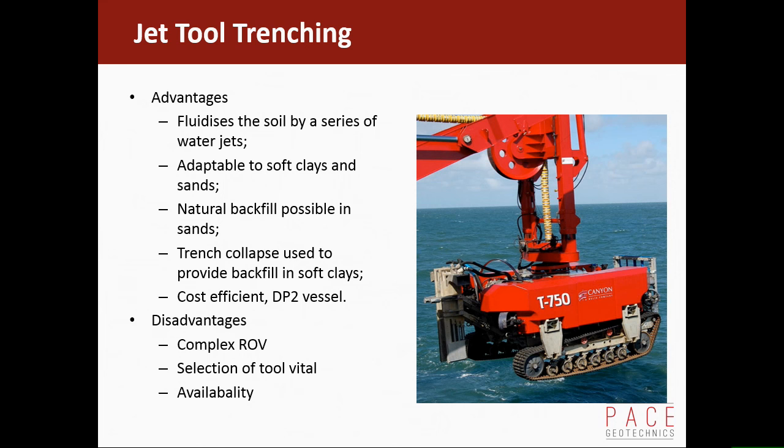Jet tool trenching is a good method of trenching in sands and soft clays. It really is very effective. One of the things in sand is you trench, you fluidise the seabed, the pipeline sinks down, and you'd usually try and have the pipeline flooded for a jet trenching operation, and then the backfill settles naturally out of suspension. So in sands, jetting is good.